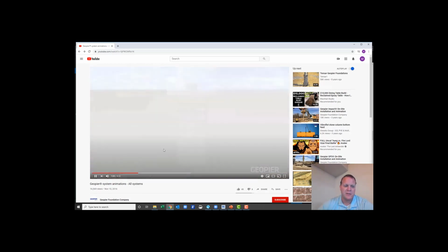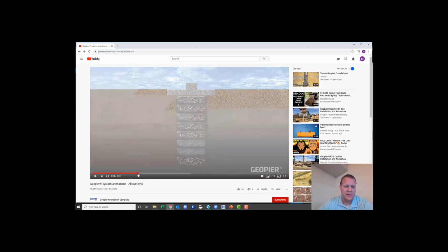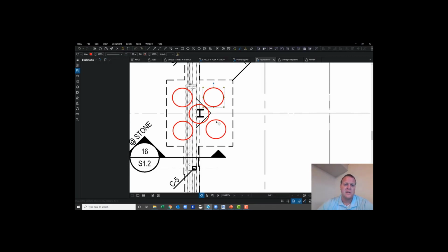So think about a pipe coming down. Well, stop, go back. Who knows if this is actually legal to do on YouTube? I don't know. Well, that wasn't where I wanted. I wanted it right there. Okay, we have a footing. The footing's actually down here. But think about a pipe going down through this stuff. Would the soils engineer like it? Would the structural engineer like that? Do we have a design conflict? Sure, we do. There are multiple designs involved here that matter, and this should turn into a request for information to the designer, and we should be asking them what they want us to do with this coordination conflict.